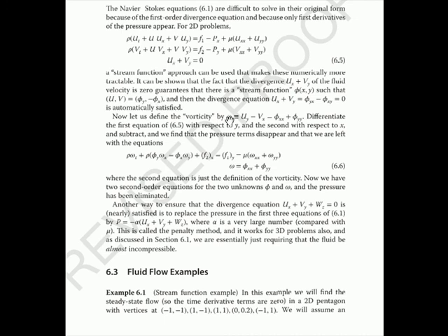phi and omega are both 0, which is a little ironic because basically that means that in terms of phi and omega, that's a fixed boundary. The free flow is a fixed boundary because the vorticity and the stream function are both 0. On the rest of the boundary, the no-flow boundary, that's actually going to be the more general boundary conditions because phi and the normal derivative are 0.